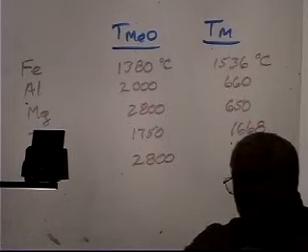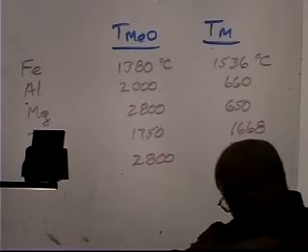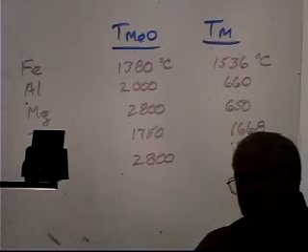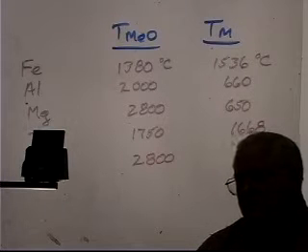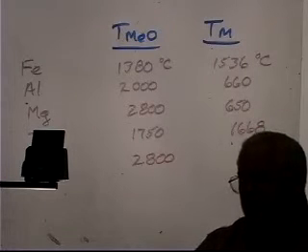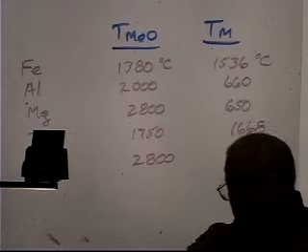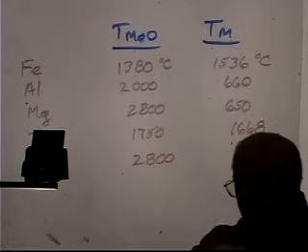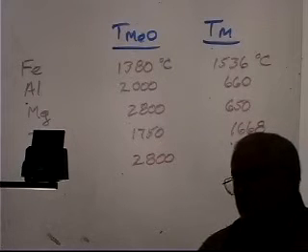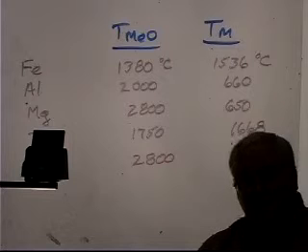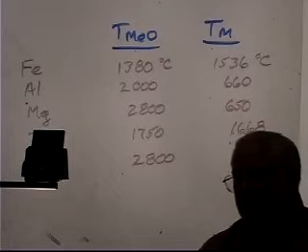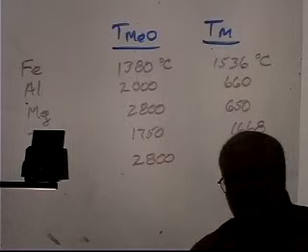They just take an oxygen lance and blow the pure oxygen on the steel, and you can cut right through the steel. And that's exactly how they cut off the great big blooms coming out of a continuous caster. They just have an oxygen lance blowing pure oxygen on it, and it just burns its way through. This is sometimes called burning steel, and literally it is burning the steel. You're using the iron as the fuel.